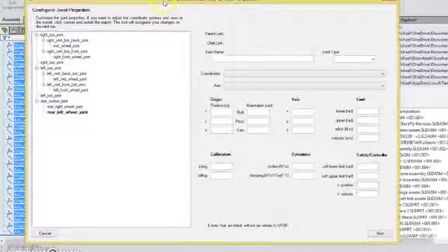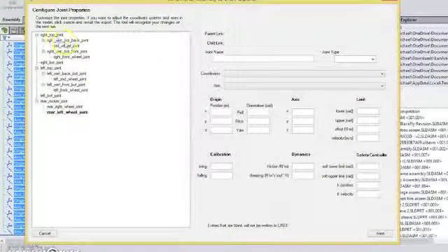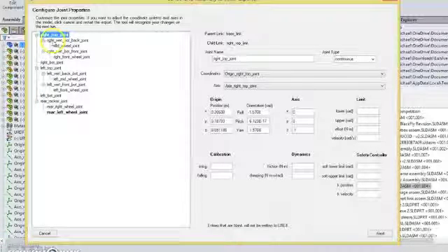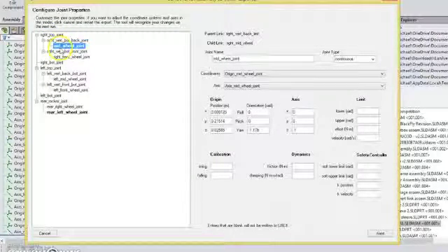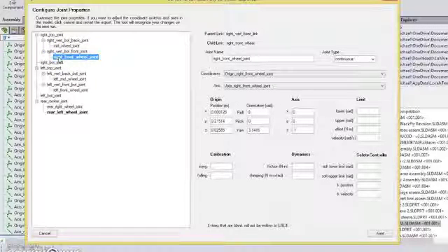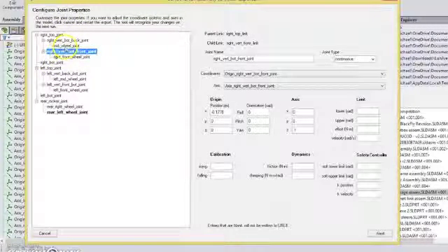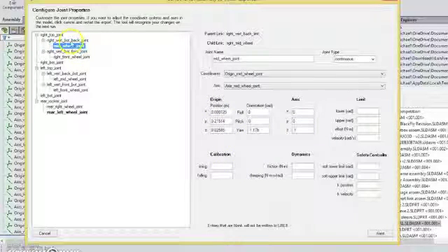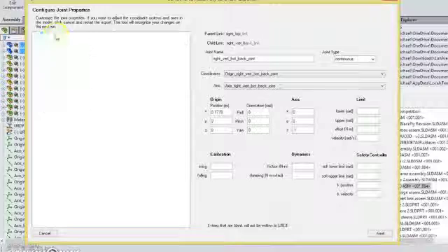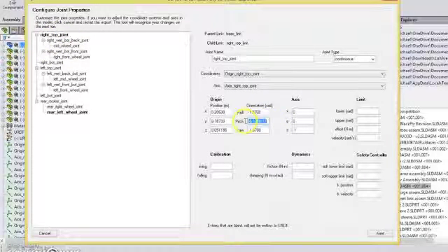Alright, so now we have our export has gone through successfully, and we can look at the joint properties and investigate to see whether these are what we would expect. So we see the axis of rotation here for the continuous joint, and then the position and orientation of the origin. Now URDF uses scientific notation. So if you get something like this, we see e to the negative 17. That's essentially 0, and you don't need to worry about that too much. You can switch it to 0, or you can leave it. As you can see, this is radians rounded.